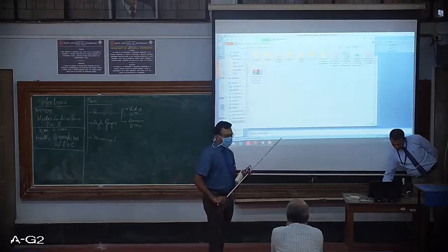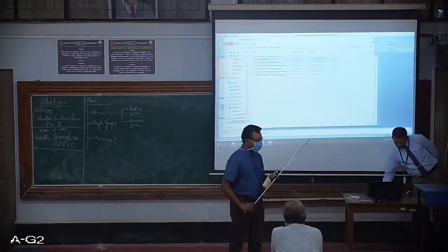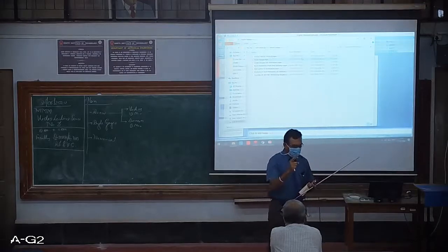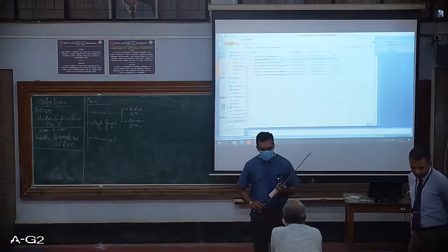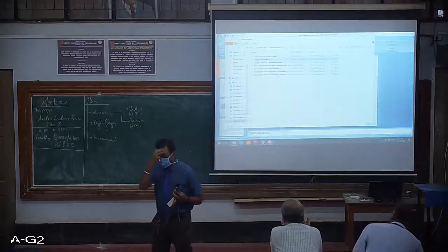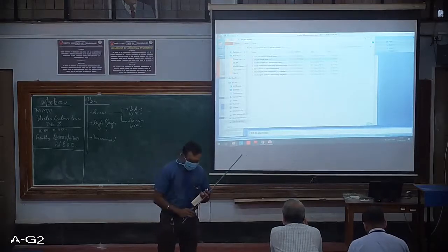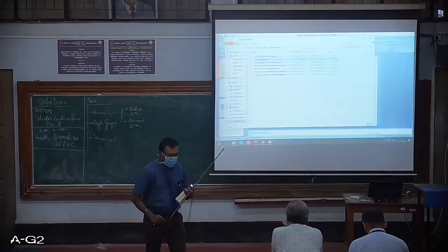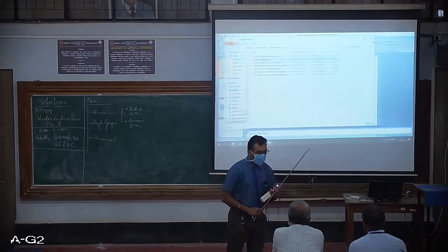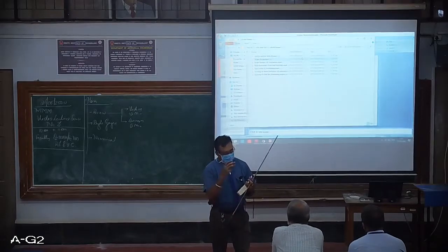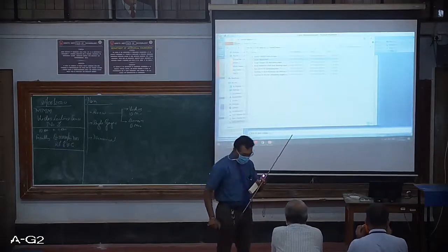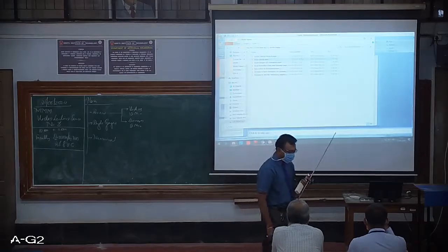Yesterday we discussed sine bar measurement, then sine center, what the limitations are, and materials. We also discussed the surface properties, then the IT grade requirement of the angle surface for a sine bar, which is around IT04, as Professor Chitnis was mentioning, never ever beyond IT05 or 6. Please understand, IT04 and anything less than that is gauge grade: 00, 1, 2, 3, 4.